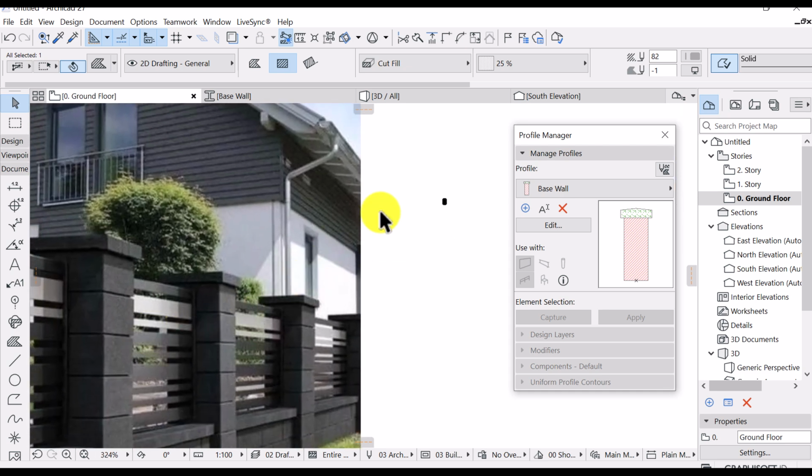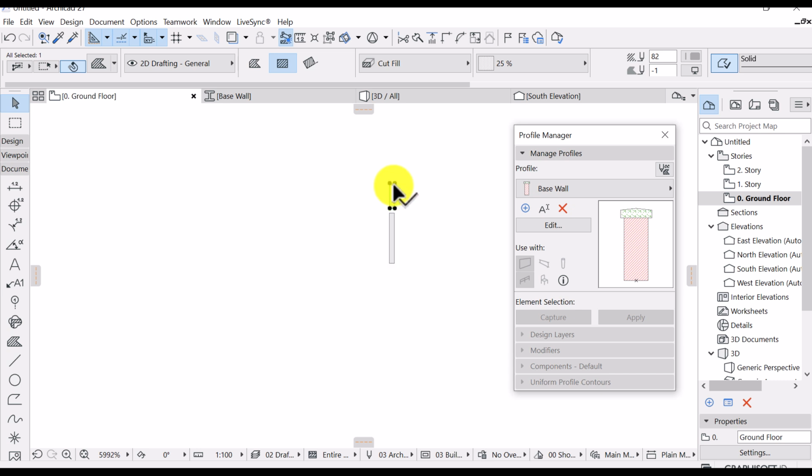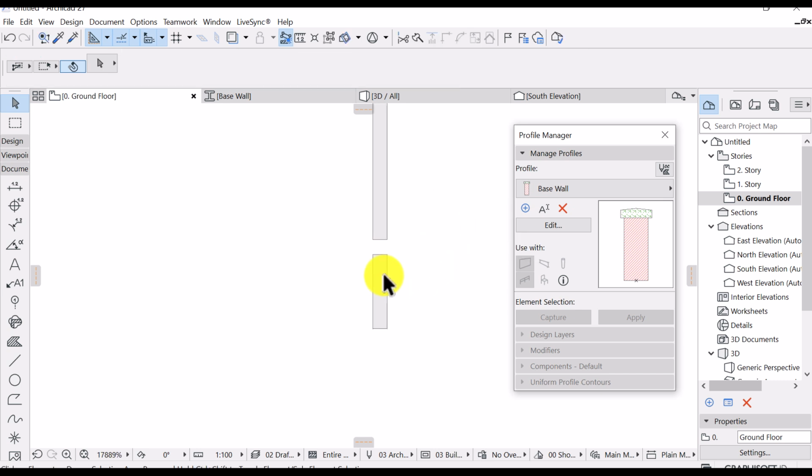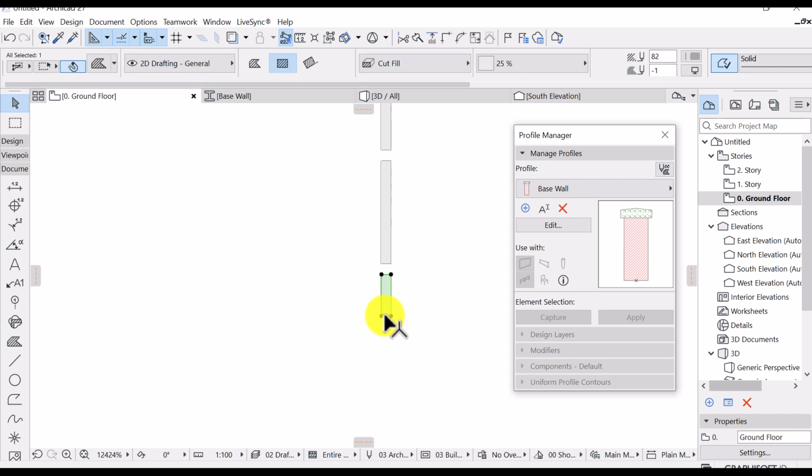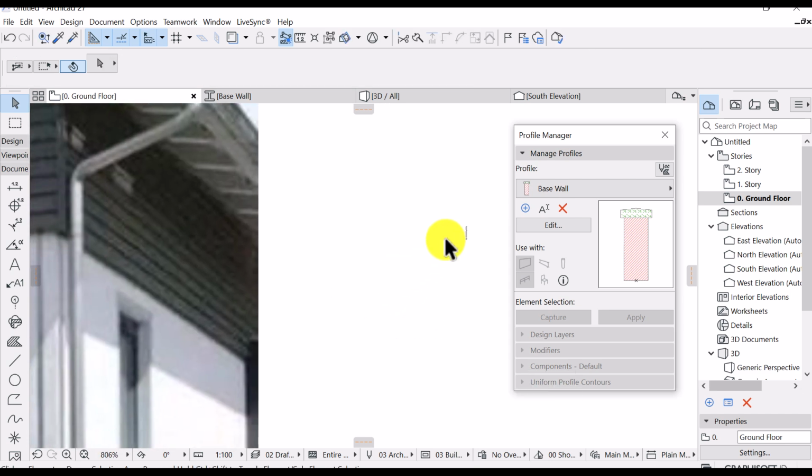And then the third one, it's a little bit of half of the first one. So I'm going to Control Shift D, put it here, Control D, move it by 10 millimeters because that's what I want, and then you're gonna push it back by 10 because it looks much lesser than the first one, maybe by 20. Okay, so we have that.